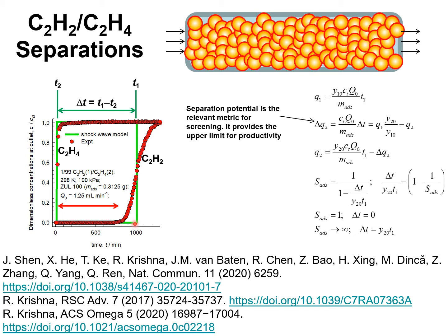The departure from the Shockwave model is primarily due to non-idealities in the gas flow within the tube, could be due to axial dispersion characteristics of the tube and or intra-crystalline diffusion limitations.